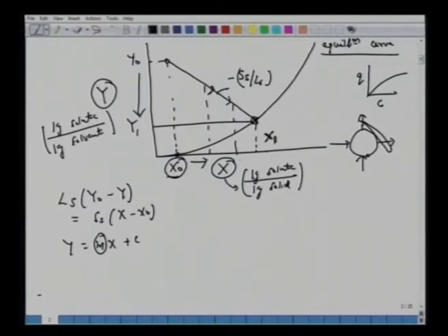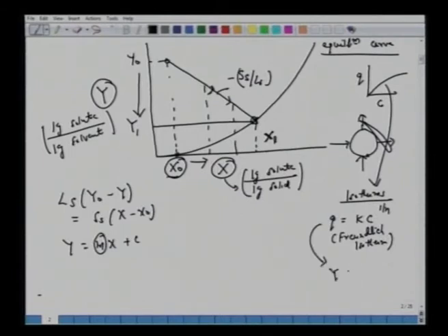Okay. So essentially what we are saying here again, all these isotherms which we used, as q equal to k c to the power 1 over n, if you talk of Freundlich isotherms, we said that is the most common isotherm from an engineering point of view, where we relate q in terms of c. This can be converted into y equal to m x to the power n.